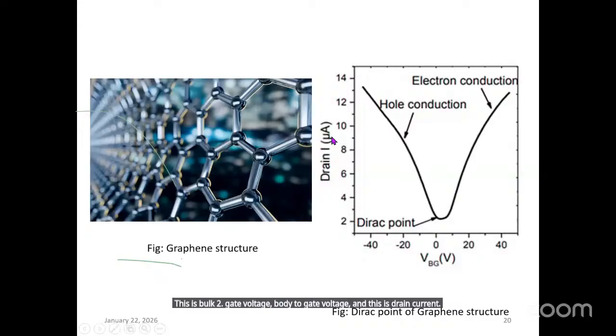If we manufacture a MOSFET with graphene as the channel material, then it has this property: when the gate voltage is positive, the flow of current is because of electrons, and when the voltage is negative, it is because of holes. And when there is no gate voltage, the device ideally does not carry any current, forgetting leakage current, and that time the device is called an off device.